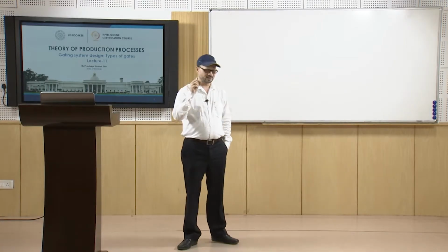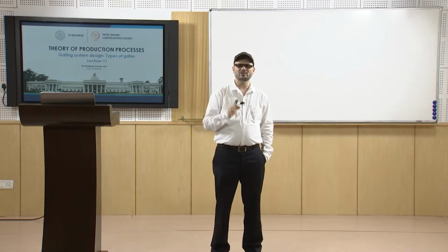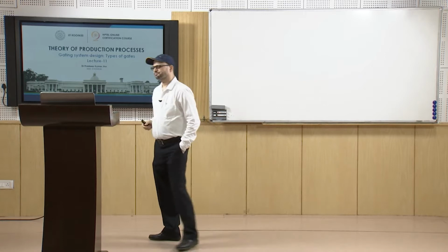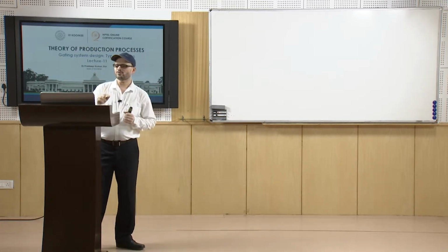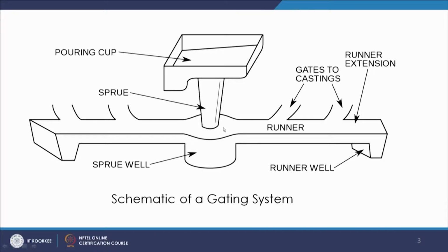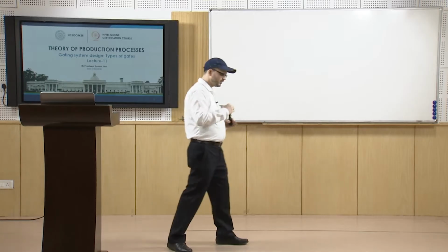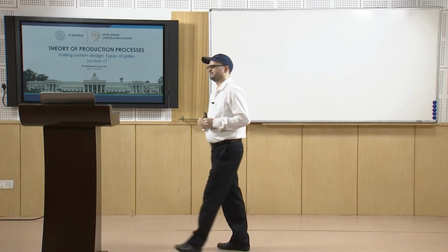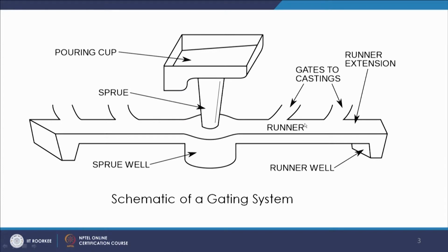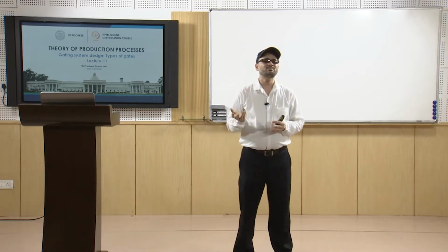From here the choke controls; it is the point where you have the minimum cross section, and then the flow is established in the domain. That is what the choke is. The choke may also be further downstream. If the choke is here, then this is the minimum dimension, and you will have larger dimensions towards this side. In that case you ensure that this is running full. In this case you have the minimum dimension and the dimension increases. So, based on this you will have different types of gating system, that is pressurized and unpressurized.